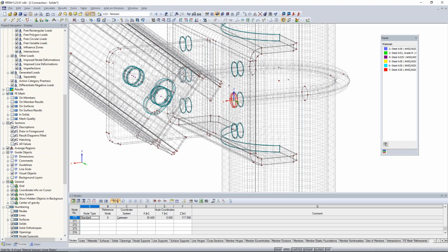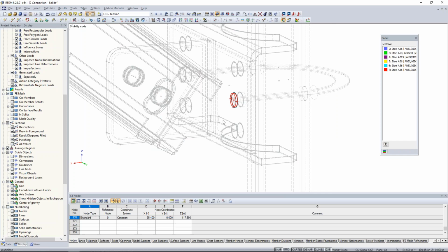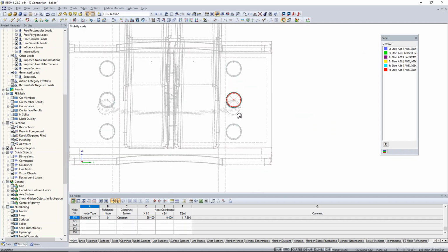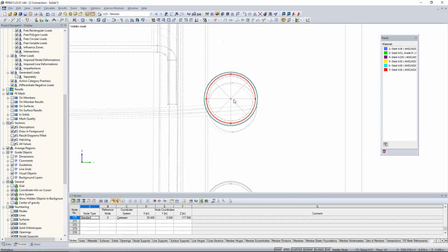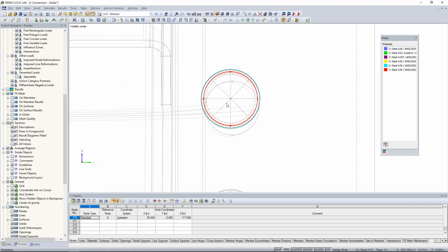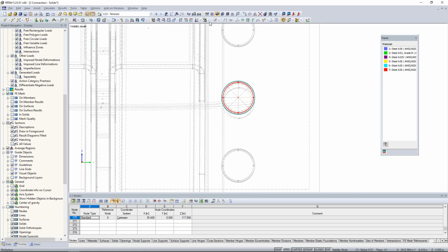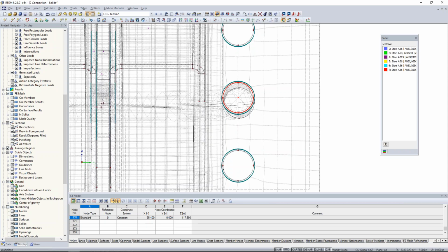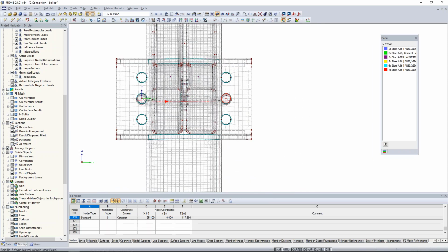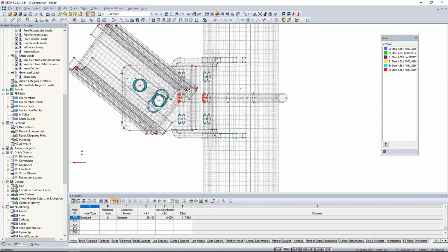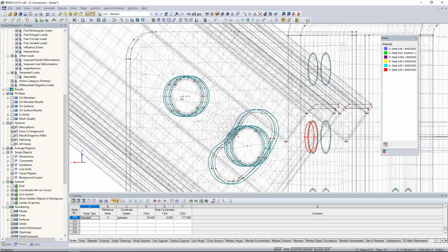And let me take a look at one of these smaller bolt solids, for example, and I'll create a visibility by the selected objects. One thing that I'd like to note when we're kind of zooming in here is that there's actually only 2 FE mesh elements across the entire length. And if we're truly interested in the stresses in our bolt elements even, we probably want to refine this mesh quite a bit. So what I'll do here is to cancel my visibility mode, and holding down my control key, what I can do here is to select all of these smaller solid elements.